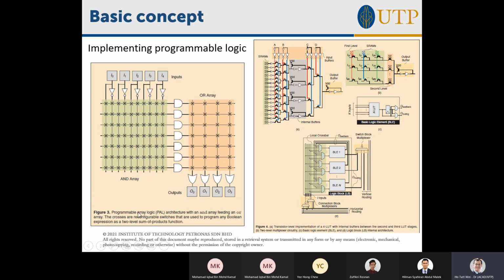In the old days, there was a type of programmable logic called PAL, programmable array logic, where the inputs just go into a set of NOT gates, AND gates, and OR gates. They have a switch matrix where they turn on the connection, whether this connection goes to this gate or that gate. So the way you designed programmable logic in those days with PAL, about 20 years ago, is you just specify these locations, but you are still implementing your logic with discrete gates. You are just programming or configuring the connectivity of the wires.